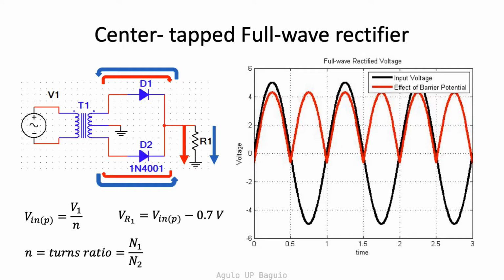The inductor that is connected to the input voltage is called the primary coil. The inductor that is connected to the remainder of the circuit is called the secondary coil. If current goes through the first inductor, current in the other inductor is induced according to Faraday's law. The ratio of the voltages across the primary and secondary coils depends on the relative number of coils between the two inductors. This is quite easily seen from Faraday's law.